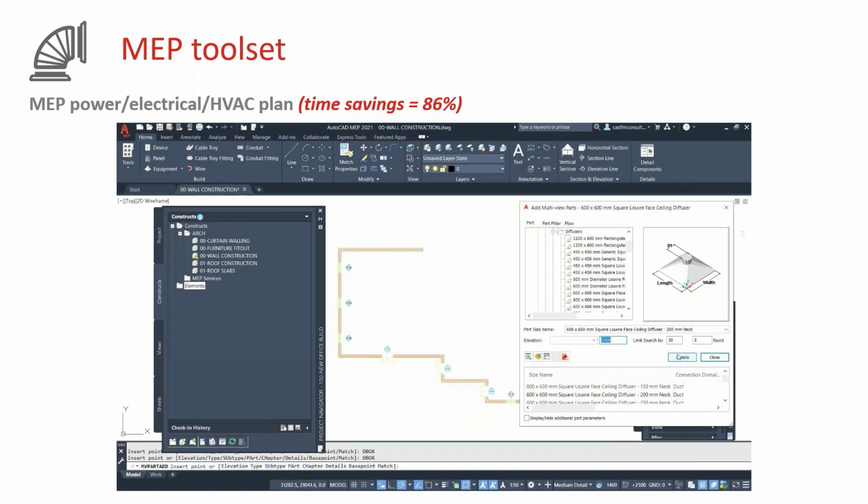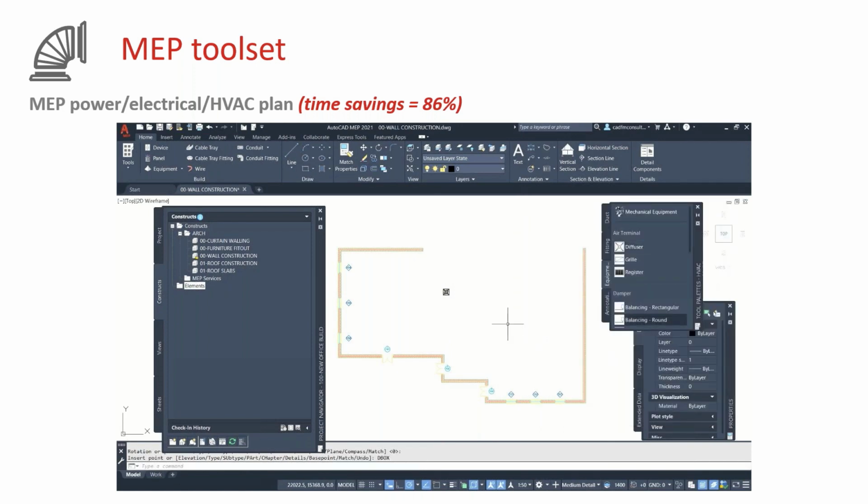They're all 3D parts, and I can specify a particular industry standard. So I've gone in there, I've just picked a diffuser with a certain neck size, certain duct size, and so on, and then I specify the rotation of it and I drop it in, and it's at an elevation there of 2,500, which is 2.5 meters in a metric environment. So there's my diffuser there. It's kind of floating in space.